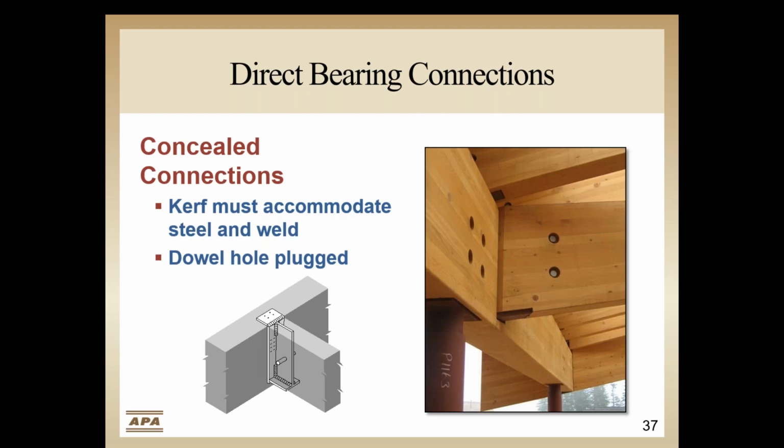There may be times that a concealed connection may be desirable. This is perfectly acceptable, as this connection isn't fundamentally different than the connections we have just reviewed, and the same wood philosophy should apply. This means providing full bearing and designs that allow the product to move. The suspended beam may be dapped on the bottom for a flush connection. The pins may be slightly narrower than the suspended beam, permitting plugging of the holes after the pin is installed.